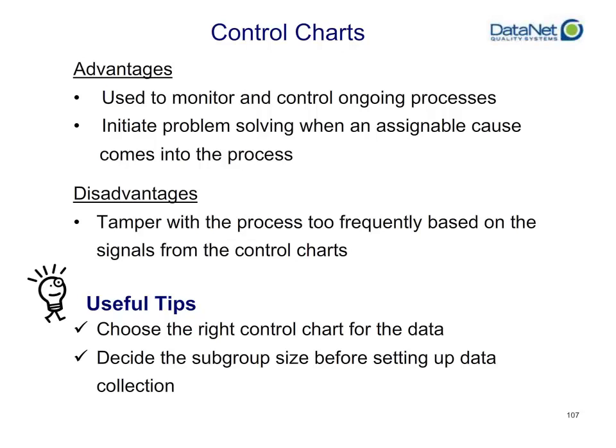Disadvantages to control charts are, again, just because the controls are what they are doesn't mean that you may not have external checks. However, if you start controlling too often or you put on too many of the control rules that you're looking for, you're going to start getting false positives, and if you start responding to false positives, you will become the source of variation.